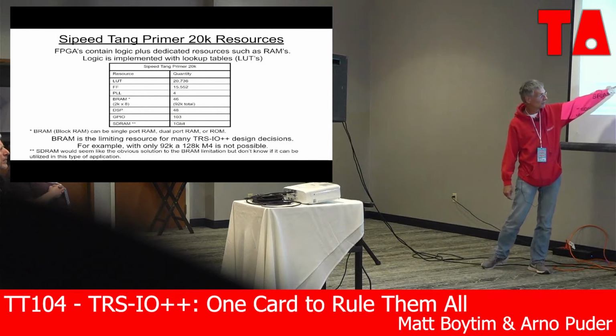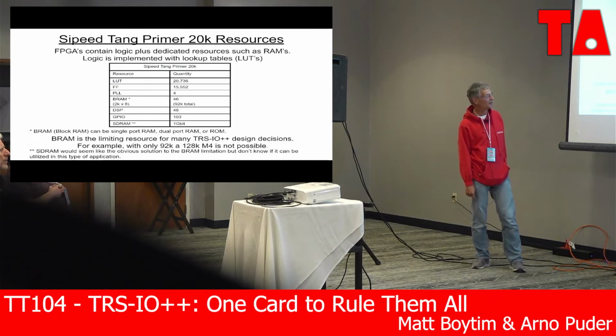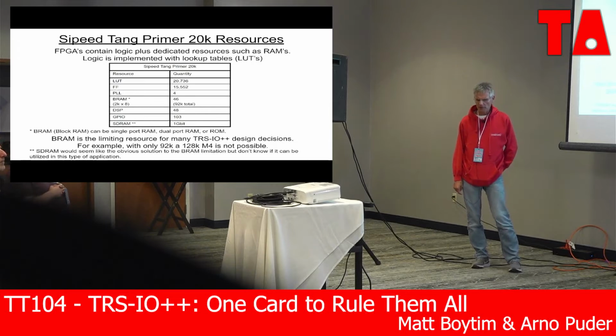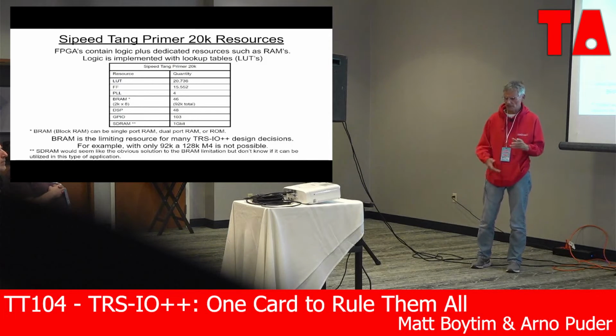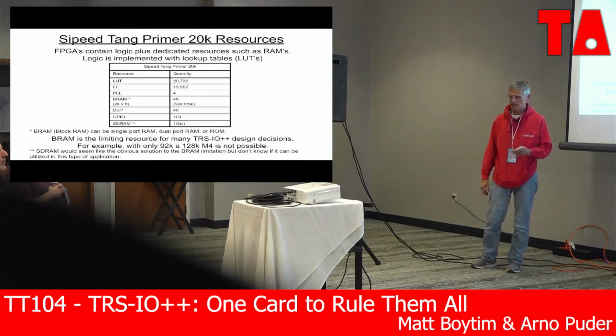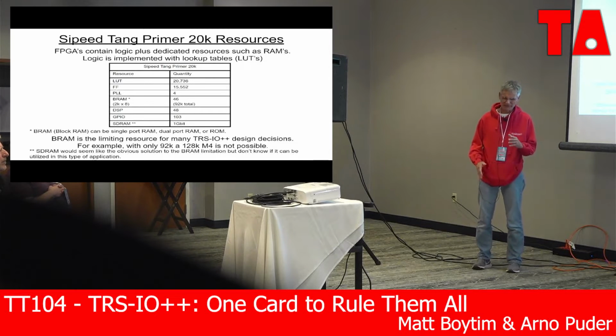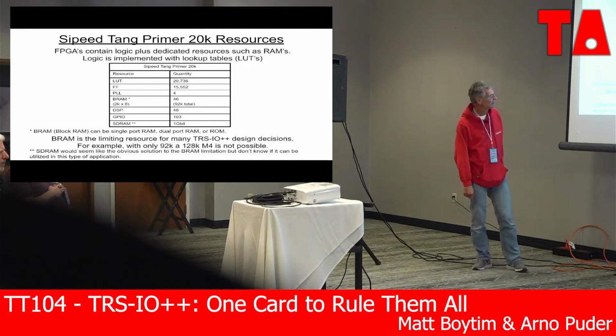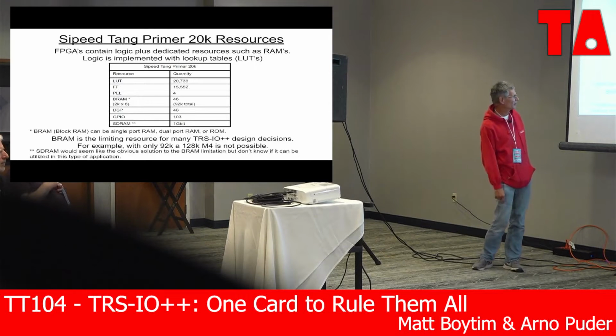This particular module has a 1 gigabit SDRAM, which would seem potentially rather nice, but modern SDRAM is fairly difficult to use. We might be able to work it in a design in the future, I don't know, but modern DRAM is not like the DRAM that you might be used to, where it's really random access. It's more transaction based. It's kind of intended to be behind an SDRAM controller, with some type of cache interface. It doesn't hook up to a Z80 very easily. So at the moment, we're currently not using it.